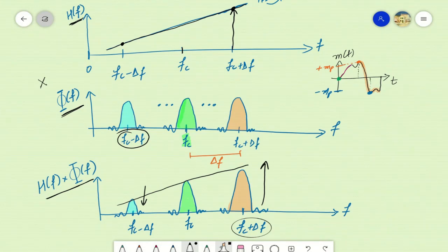So along with the fluctuations in the position of this sinc, which represents the information signal, we will experience a directly proportional change in the amplitude of the output signal of the filter,